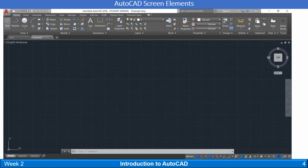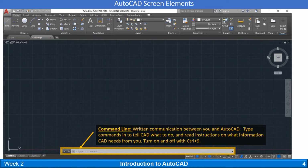Okay, so how are we going to put commands into this thing and tell it what to draw? Down here at the bottom is the command line, and if you don't see this command line, or if you accidentally hit the X and exit out of it, just hit Control 9 and that will get it back up there.